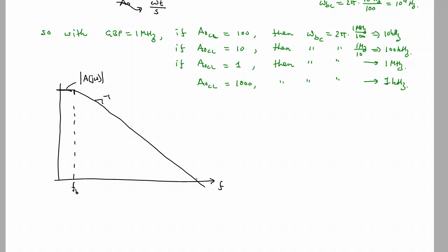It crosses over here, has a unity gain of GBP or FT. Now we come along and we design a non-inverting op-amp that's going to have a gain of, let's see, this would be 1, 10, 100, 1,000, 10,000. Let's say this was a gain of around 10.